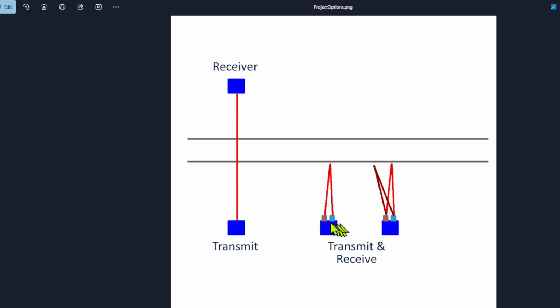Now what I was concerned about is obviously it sends a beam out. As the train comes by, it reflects that beam back to the receiver unit. However, the beam doesn't go out in a straight line, it will sort of form a cone. So my concern was if I got light going out to the left or to the right, I could get weird reflections coming back into the receiver. So if you're building a project like this, sometimes it's quite useful to do some tests. And I'm going to show you how I tested these units.